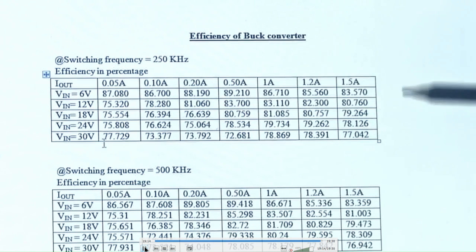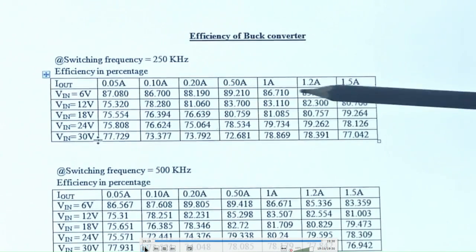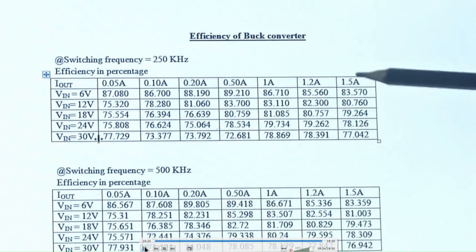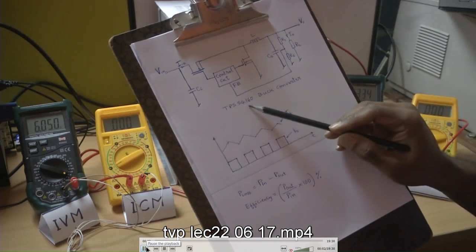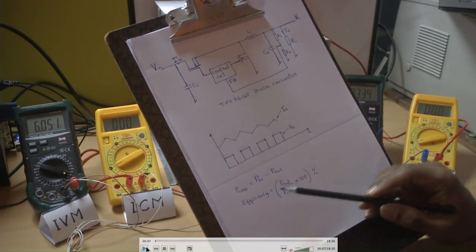Essentially what we are saying is that this table should be prepared, and you should find out in this matrix where you get the maximum efficiency and whether it matches the required load currents and load output power, whether it will allow the buck converter to give you the best efficiency. Why is that important? Because energy harvesting is an input to all these systems, and therefore unless you have highly efficient systems, these systems may not give you good battery life.